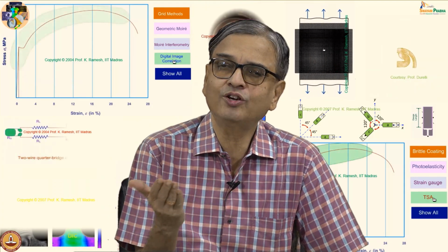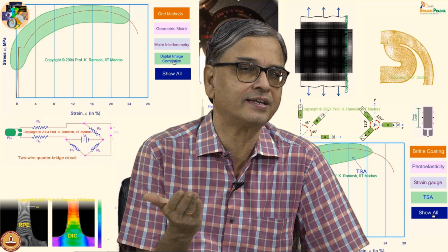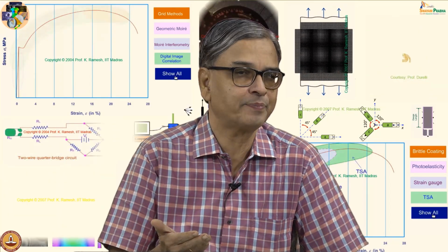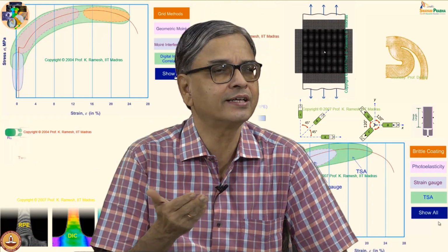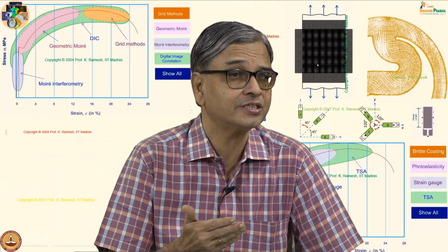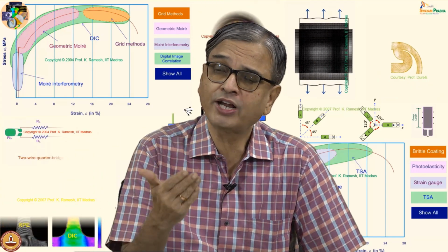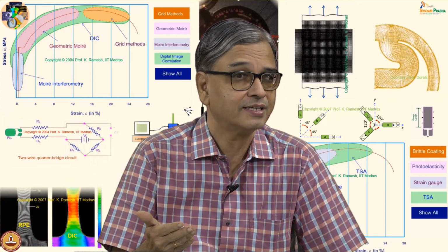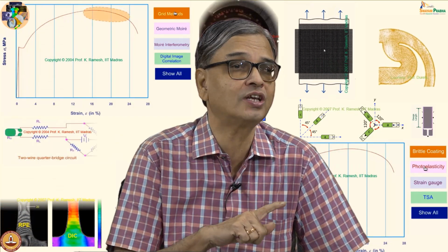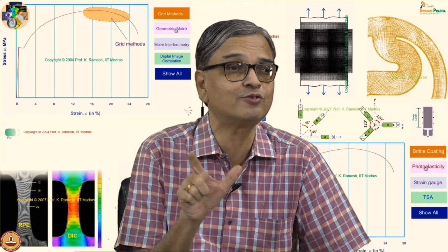And with a scale, you can measure 0.5 millimeter reasonably well. When you go to a vernier caliper, you can go down to 0.01 millimeter. When you go to a screw gauge, you can go down to 0.001 millimeter. But you also find the range with which these measurement methodologies can be used keeps reducing.